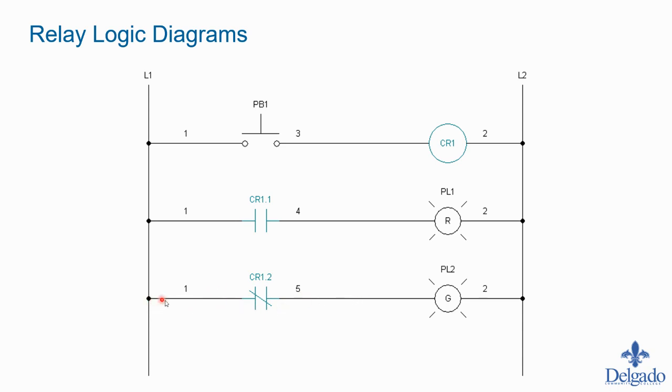So right now, the current is coming on rung 3, it's coming through this contact, and it'll come to this green LED indicator and complete the circuit. So that means the green light will be on. So basically, push button's open, red light is off, green light is on. Real simple.